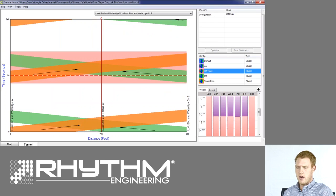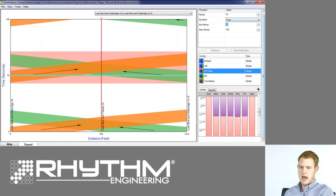In this specific configuration, you'll see that there's 3 intersections coordinated with a wide dynamic period range, and you can see that by the pink band in the middle of the time-space diagram. So if you want to adjust what the dynamic period length range is, you select the dotted line in the middle of the time-space diagram and then view the property sheet in the top right, and you'll see that there is a minimum period and a maximum period defined for that configuration.